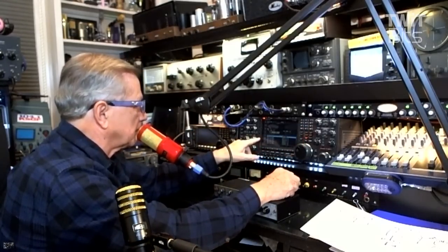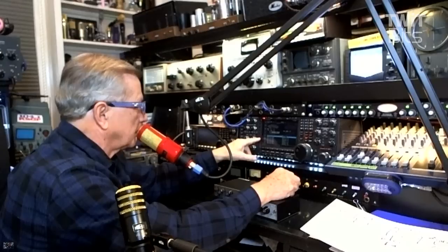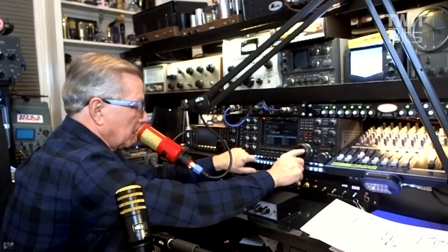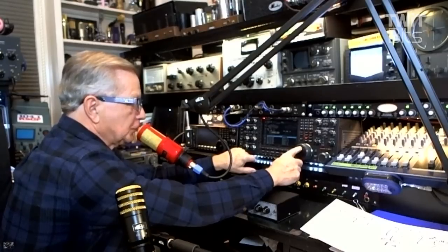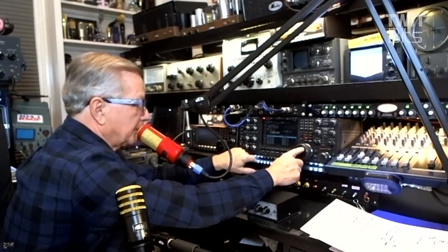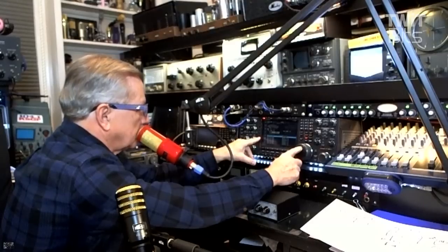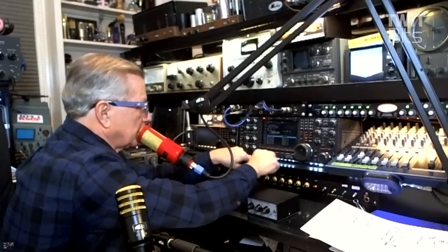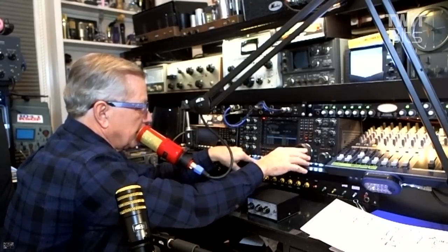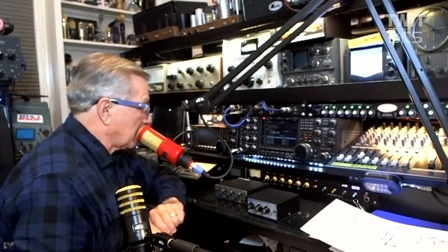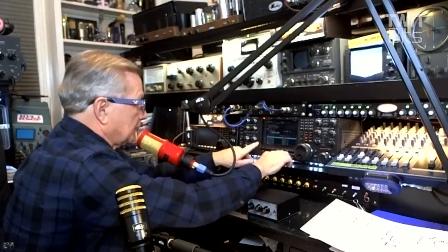Now we're going to go to a transmitter, and there are many, that has a wide filter. Now bring on the PR40. And you see it makes a huge difference as to what's going on with the audio. Now, if you're wanting to do contest work, beautiful. We're going to go to the mids. We're going to punch up all we can of the highs, and we have a transmitter that's going to cut through and make you sound great in a pile-up. Is it beautiful audio? Of course not. Is it good? Absolutely. For contests, for even nets and places you need to get your transmitter through.